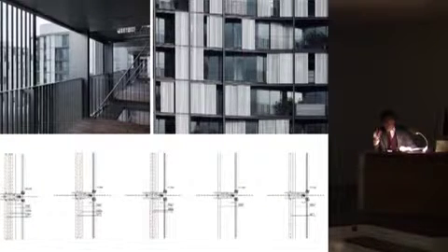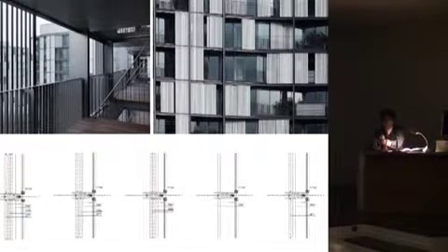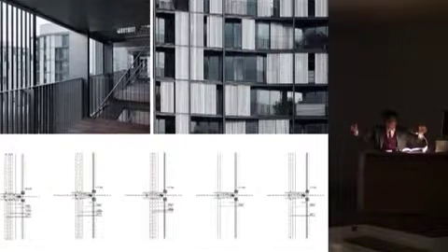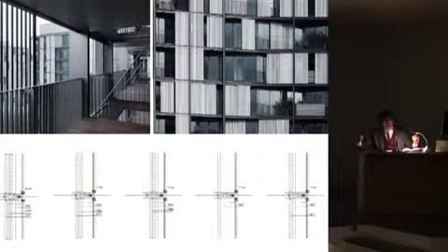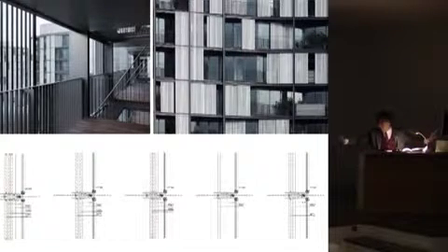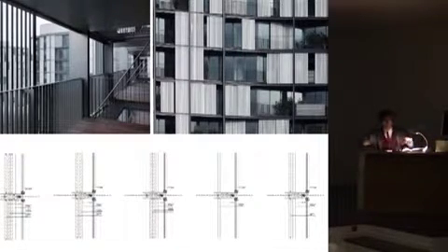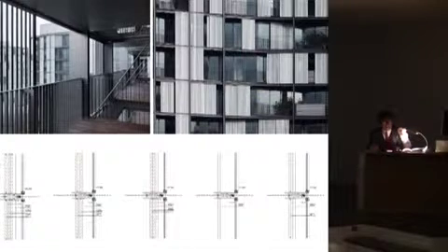Imagine 1 square meter of terrace, 1 square centimeter of a drain. So that's the kind of estimate that I work on. And then you have a pipe of 40, 4, 6, 60. I prefer to work on many and well distributed to prevent the water from running. And then, you know, these gutters can be flat. They're short and they drain here and there, so they don't need a slope.